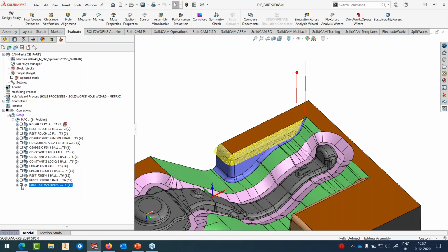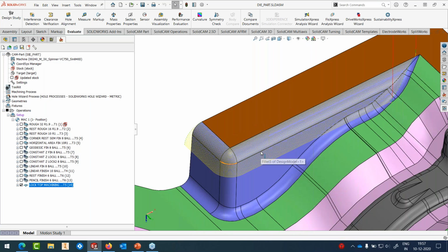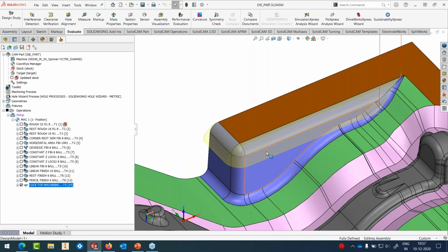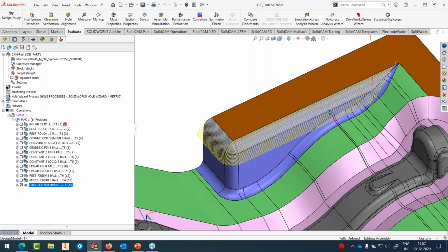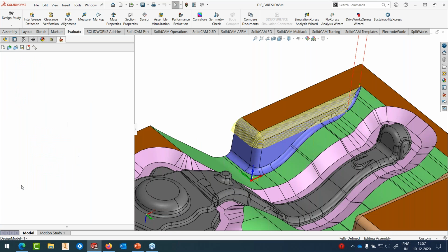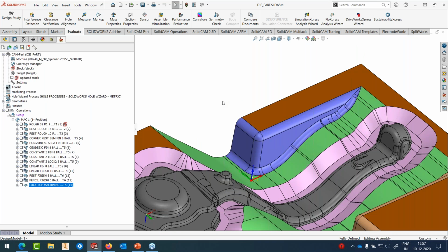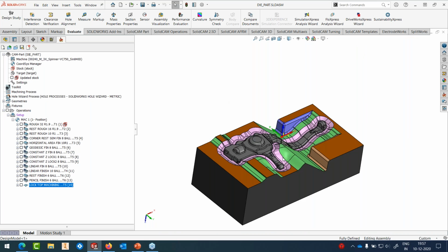And this is how my toolpath looks. So you can see the power of HSS: a smooth toolpath on a group of surfaces without creating any boundaries. Just pick the surface, pick the probable gouge check areas, and calculate the toolpath. Clean, clear toolpath. Okay.